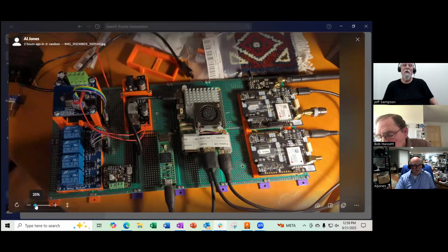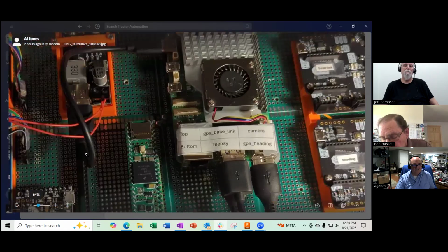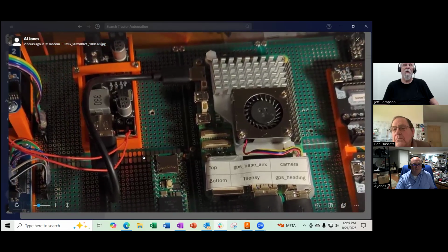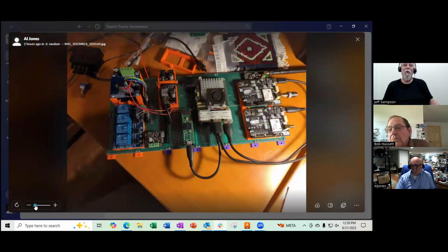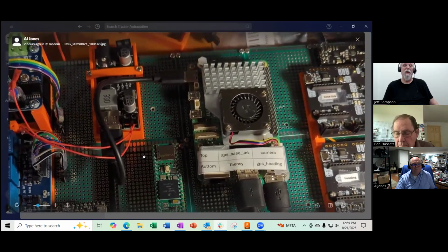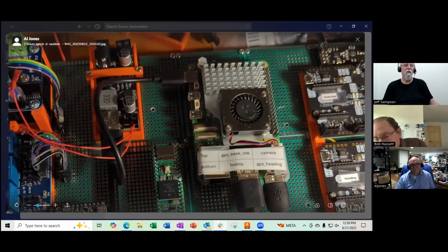Sure. Something to keep in mind on that, the USB-A cable coming out of that thing may not be rated for the 5 amps that you're looking for. And when you bought the cable, did it claim that it was rated at 5 amps or 18 gauge wire, whatever the tricks were on that? Yeah, I don't remember. I'd have to look because as you can see, it's a rather short cable. And so I don't actually remember what the specs are on it. I assumed, hey, it's just a couple of inches here.